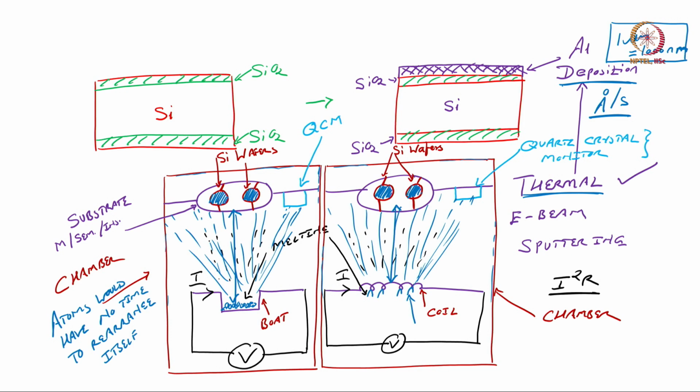But the question comes: if you apply a voltage and the current starts flowing, how will we control at what time the evaporation should start, because as soon as the material is loaded, it melts and starts evaporating, is not it. So, we need to first understand that the material is completely melted, and only then should we start evaporation. So, there is one more tool within this one, which we call a shutter.